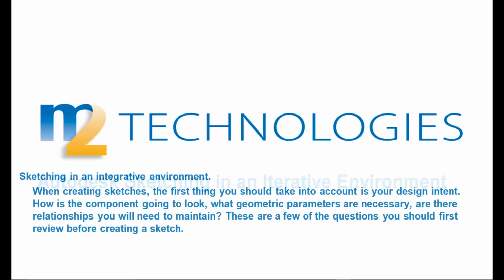So, what is sketching in an iterative environment? Well, the first thing you do when you start a new design is try to understand what your design intent is. You want to focus more on the shape and its relationships to other pieces of geometry than just the size or the dimensions. Having an understanding of each of the features and how they will relate to each other long term will give you an advantage when it comes time to edit a design.